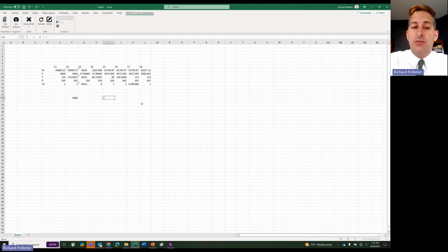So obviously the one is you can always type these, right? So I can do SC, which is going to pull up all of the different Sim Central functions, right? Hence the SC. All right, so again, Sim Central, Aviva Process Simulation, same exact thing. So I could go about typing these in, and you just have to know what the arguments are, or use some shortcuts to remind yourself what the arguments are, and then just type in the various arguments, and that'll be just the same as using this insert function, right?